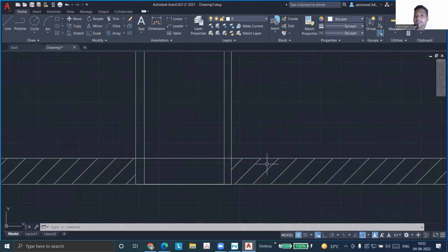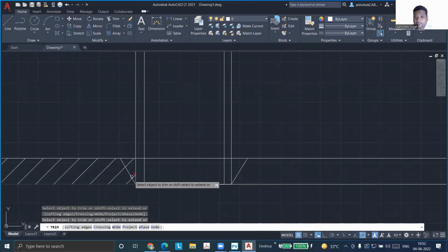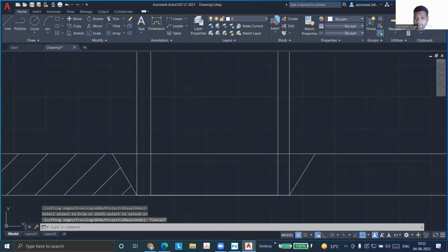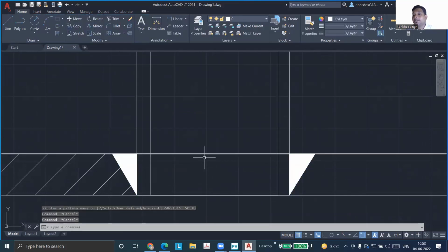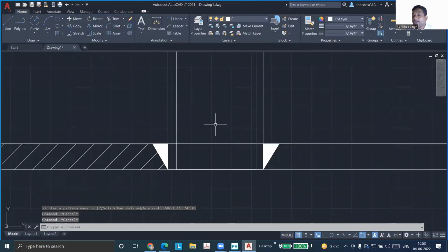So if I have to weld this nozzle to the shell, we create a hole for that set-in. We provide a weld edge preparation to that shell. We call it WEP. And then we will weld here. This is the weld. This is how we follow, right?